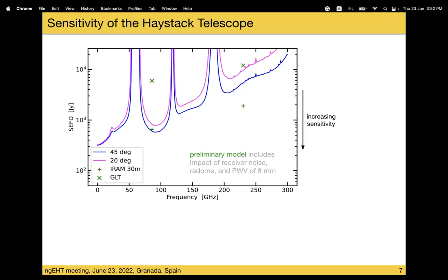And here you can see the atmospheric attenuation curves. You were asking about this. These are lines of oxygen here, water vapor, and as you go higher and higher, this value drops. Since we are at sea level, and this is the elevation of the telescope, you go through more sky when you go down in elevation, and so your system temperature increases mostly.